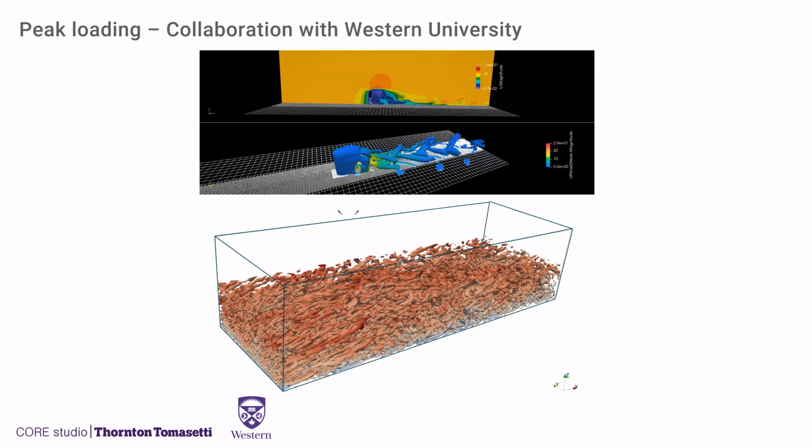Key for structural loading studies in CFD is the level of turbulence and the inlet conditions, to replicate basically air over the Earth's surface. So velocity increases by height. I don't want to go too much into detail, but velocity increases over height, and there's also turbulence in the air, and that turbulence causes gusts to appear.